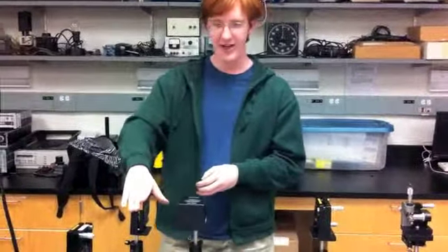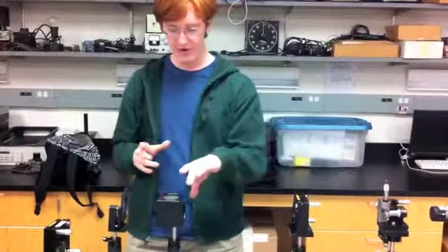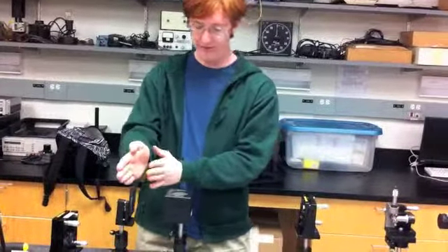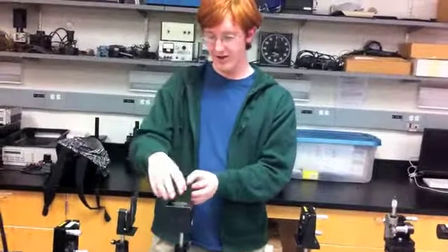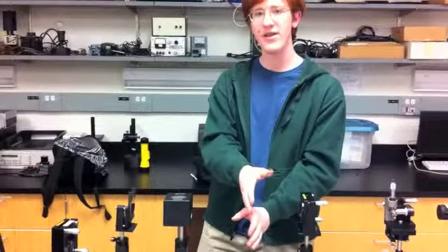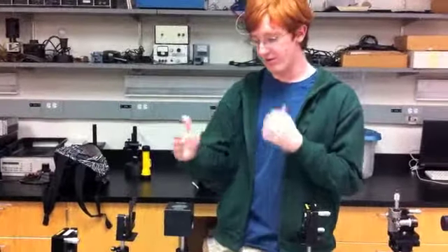So in this case, we have a flat mirror. The light will come through our system, come out collimated, pass through the shear plate, come off the flat mirror, and then back into the shear plate and create fringes. Next, we use the same type of technique to profile a lens. So in this case, we put the lens before the shear plate and again measure the fringe spaces, shear distance, and angle of the fringes.